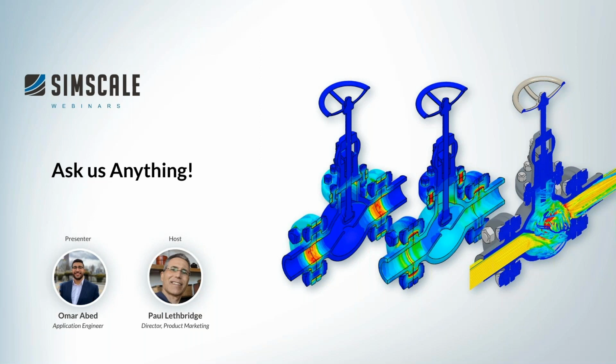But what is usually done within CFD simulations is extending the inlet or extending the outlet where you're defining that flow condition, so that you have time to resolve that contour within the simulation organically, rather than having to define it yourself. So you're able to do that wall modeling internally.